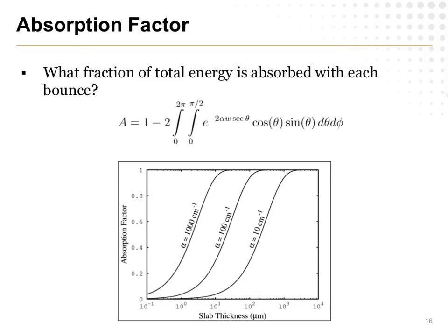Fun fact, the attenuation constant for various semiconductors varies wildly. So these are just some curves that you find when you run this calculation. A very low attenuation means I can have a very thick slab before I have any serious absorption. And a very high attenuation means I need a very, very thin slab, say less than a micron, or else I'll lose half my power in each little bounce. I believe most semiconductors fall in between, where you need somewhere between less than 10 but more than 1 micron or so to avoid serious attenuation.